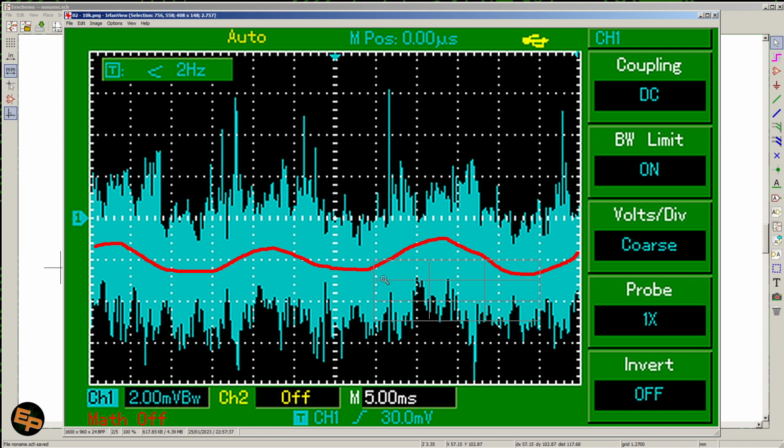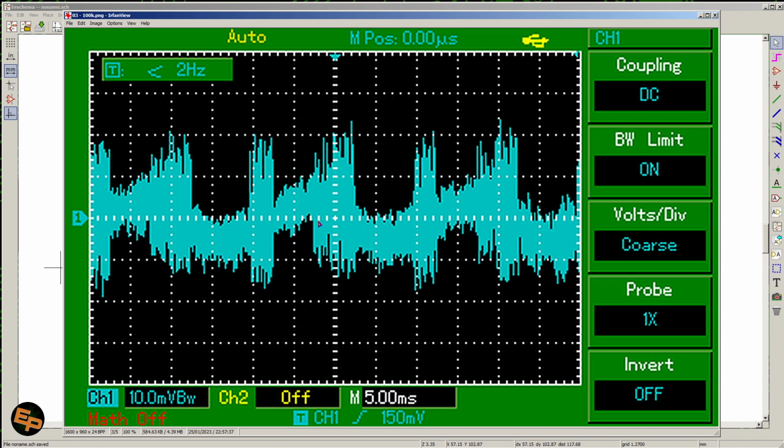The best way of measuring the frequency is to count how many divisions you have per period, and calculate the reciprocal of that, so 1 over how many milliseconds or microseconds you have. Ignore the drawing that I did earlier with my hand. The signal here has 50 hertz because this is what I have in my wall, 220 volts, 50 hertz. This will become increasingly obvious in the next examples, so I will move on.